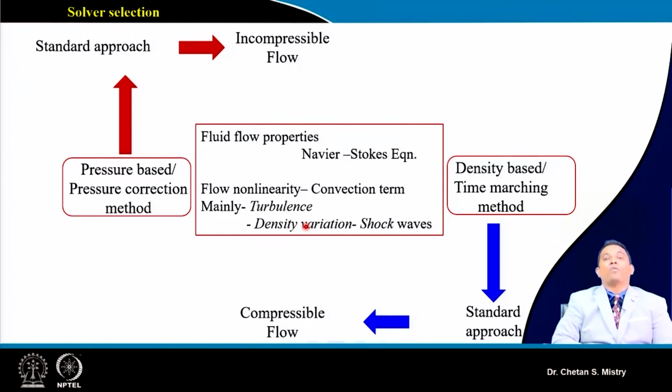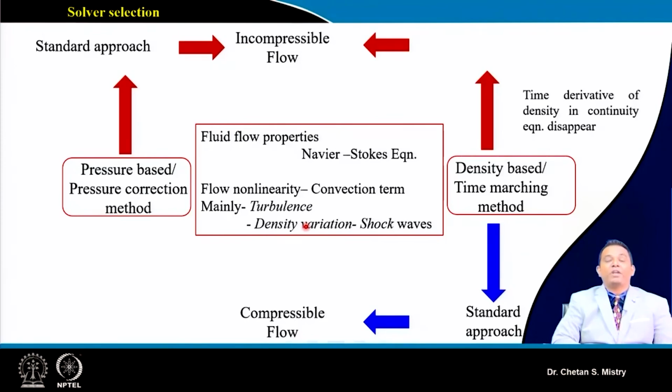Someone will say, no, I want to use my density based solver in order to solve incompressible flow rather than compressible flow. Then the time derivative term for density in the continuity equation will get nullified, or it will disappear, and we will be using the preconditioning method.